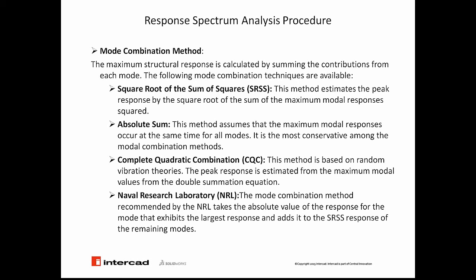The first one is square root of sum of squares, SRSS, which estimates the peak response as the square root of the sum of the maximum modal responses squared. We have other schemes, such as absolute sum, complete quadratic combination, and Naval Research Laboratory. We can definitely provide more information if you like, but we are not going to waste a lot of time on the details of each method.